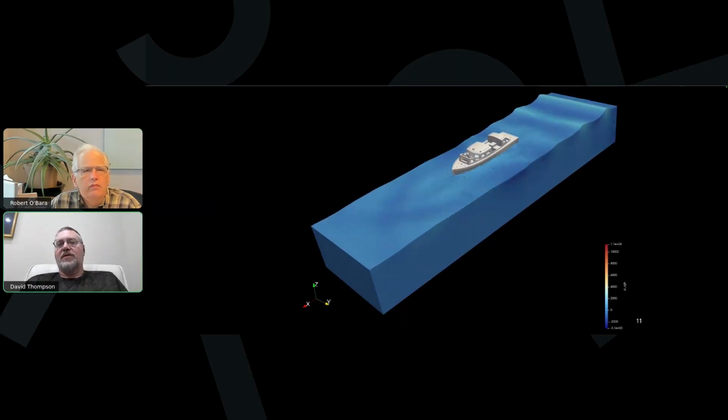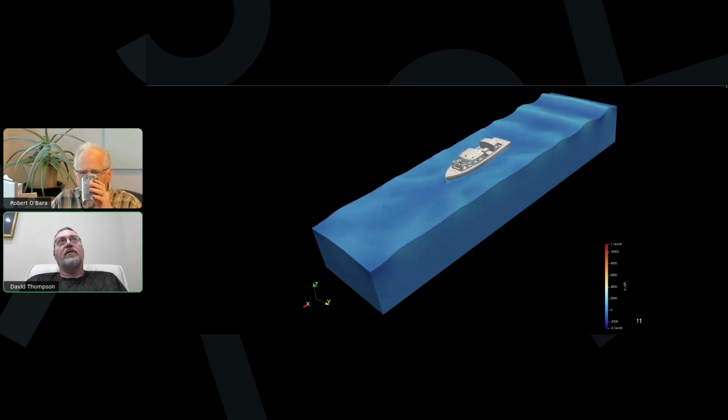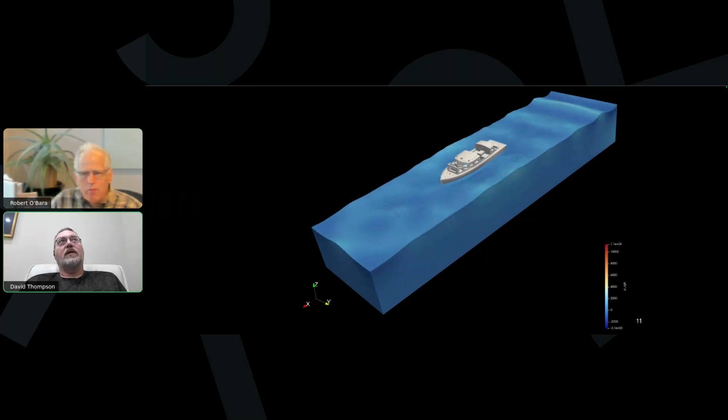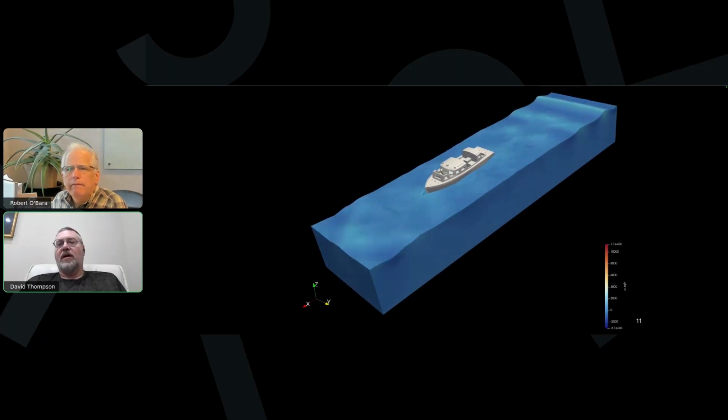I'll just note real quick. This is the simulation I configured. It's showing the alpha water thing being iso-volumed, so that's why only the water surface is showing, and the coloring on the water is the pressure minus rho gh, so that you can see things besides just the pressure increasing with the depth.